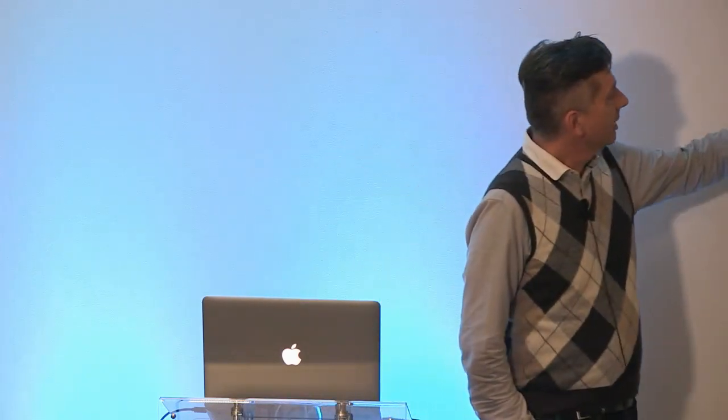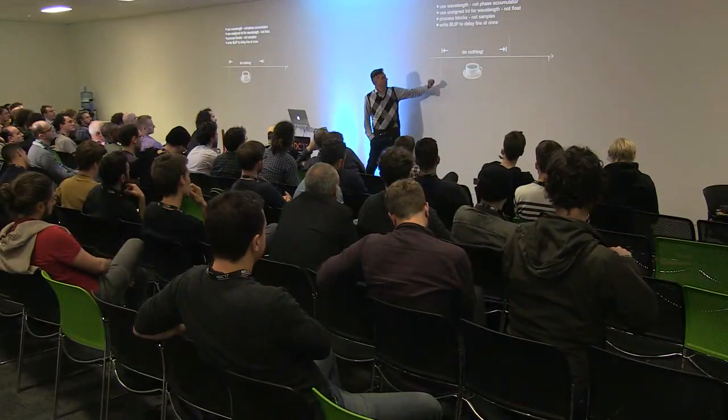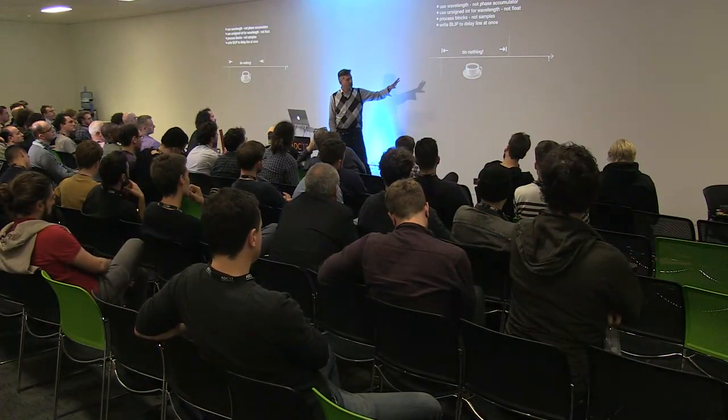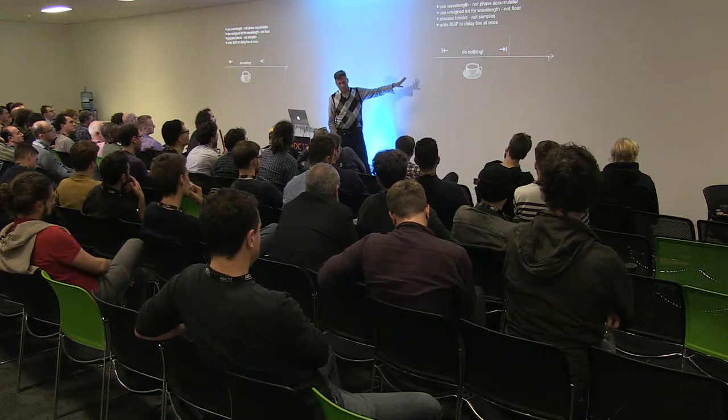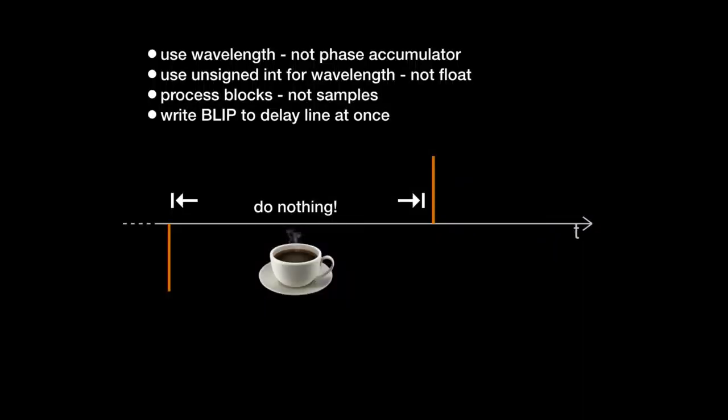Another thing to note about this, because we're operating in time, and not with a phase, the wavelength actually determines the workload. This kind of signal processing, if you leave away the integrator, is independent of the sample rate. We might even come to the perverse situation where increasing the sample rate might save you power because you have more relaxed conditions, you can work with smaller blips.